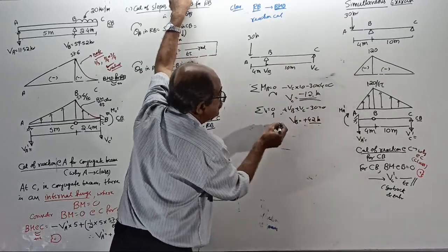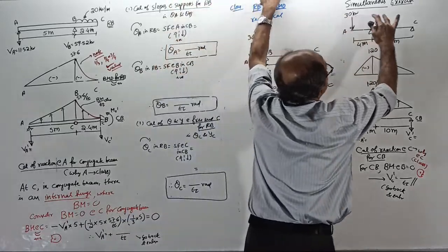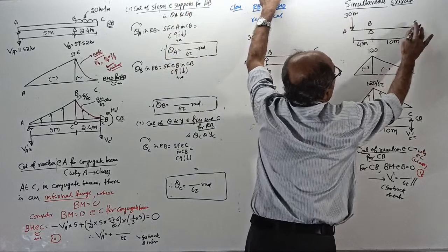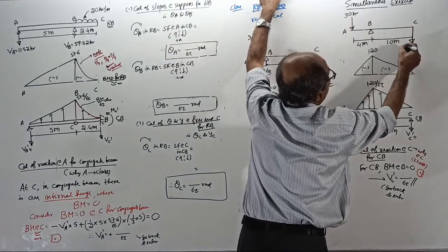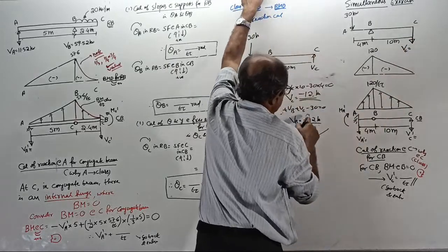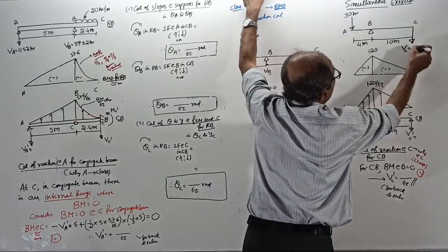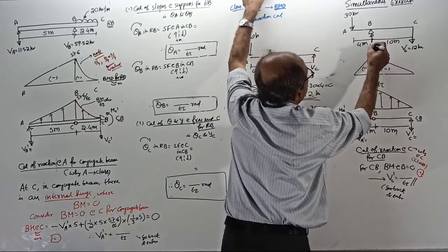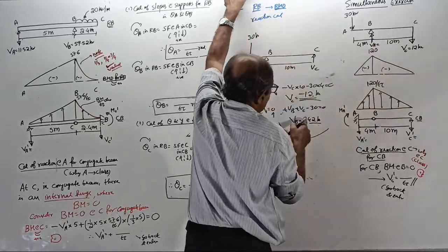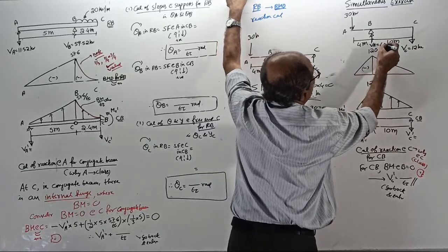Now, start the question. Neatly put the beam. This reaction you got negative, so what do you do? Write a downward reaction. VC equals how much? No minus now, 12. Why? We reversed it. And right here, VA equals how much? 42 kilonewton. Enter there.